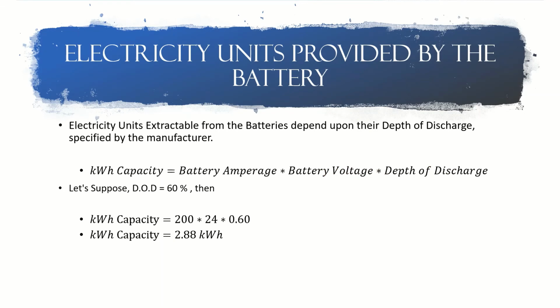Now, to calculate the amount of electricity units that we can actually retrieve from the battery, we have to know about the factor of depth of discharge. Manufacturers specify the depth of discharge of the batteries. Different battery types have different limitations of depth of discharge,